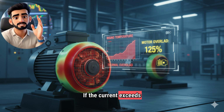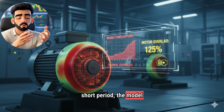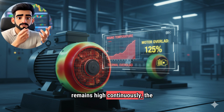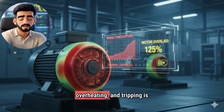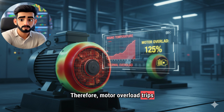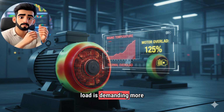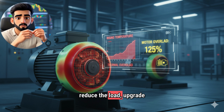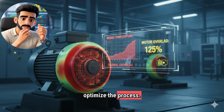If the current exceeds the rated current slightly, but only for a short period, the model will tolerate it. However, if the current remains high continuously, the thermal model will indicate the winding is overheating and tripping is necessary. Therefore, motor overload trips should not be taken lightly. This means that your load is demanding more than the motor's design capacity. You may need to reduce the load, upgrade the motor rating, or optimize the process.